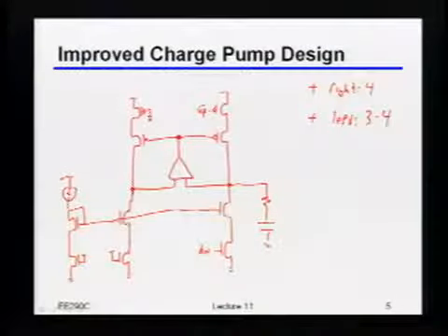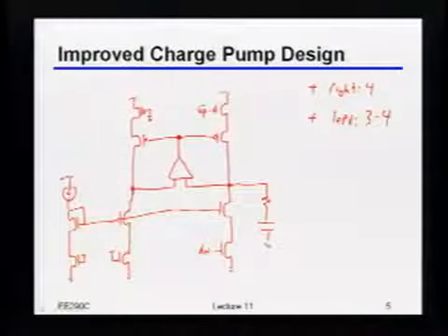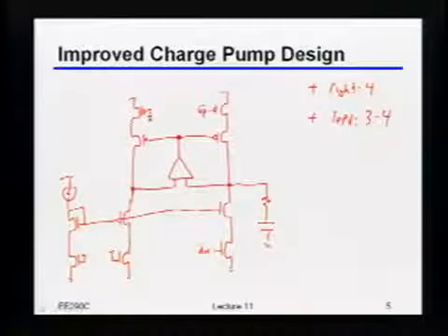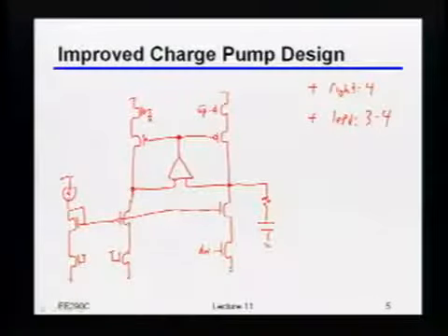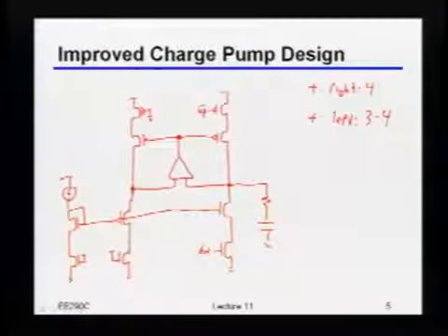So in general, how do you decide what's plus and what's minus? Negative feedback should be stronger. Yeah, the negative feedback is the loop that you want to quote-unquote win, right? So how are you going to know which loop is going to win here? You break both the ends of the op amp and put a delta V source and see what comes back. In this particular context, what is it that you care about in terms of what's going to determine which gain is larger? The voltages on the two ends.